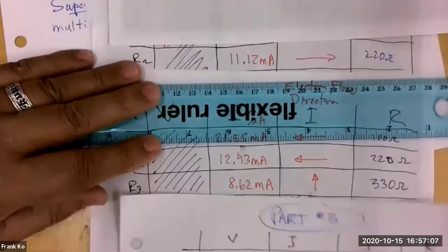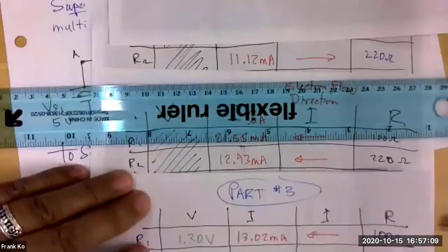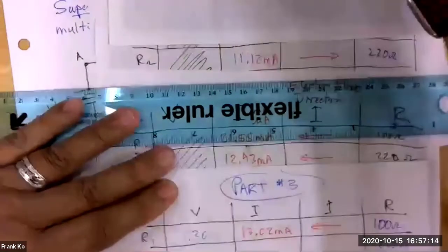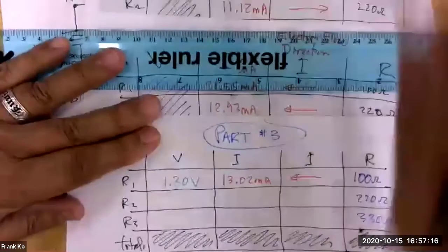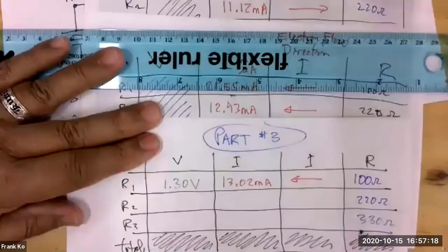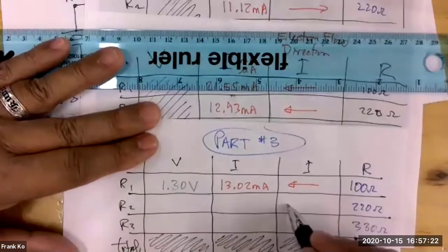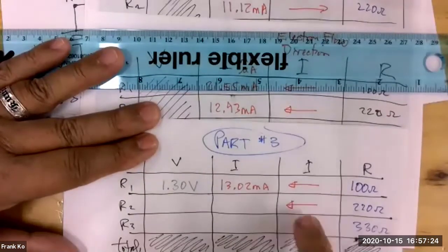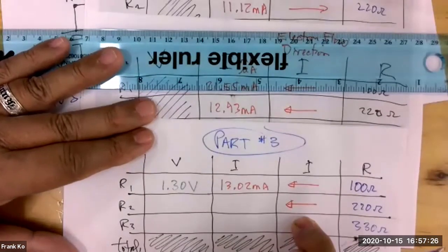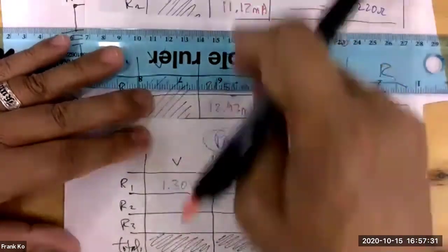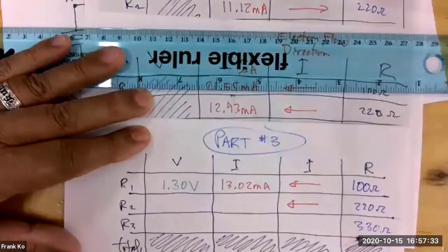Trust me, you don't want to move the paper around too much. So our final direction of current through here, and I can slide this over this way, is going to be to the left, yes? So for R2, it will be to the left. Is everybody okay with that direction, and how do I determine the final amount of current? Do I add these two up, or is there some subtraction involved?